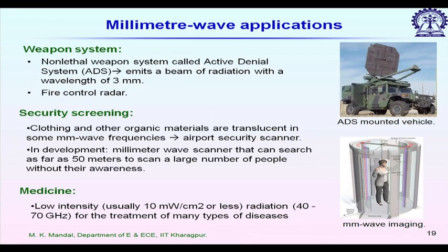Some more applications. Weapon system. It is a non-lethal weapon system called active denial system, or ADS. You can see it is mounted on a military truck. What it does is generate a high intensity millimeter wave signal, and typically it uses a frequency for which the wavelength is 3 millimeter, and when it falls on any person they will have a burning sensation, but due to the size of this system it did not become popular.